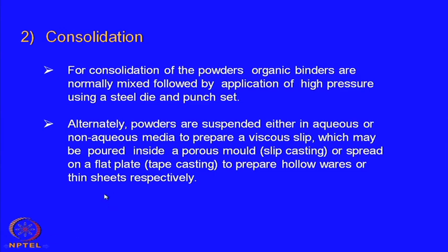These thin ceramics can be made by starting with a viscous slip, which in this case is most of the time a non-aqueous slip made with a volatile solvent. That slip can be spread on a flat surface to form a flexible tape.